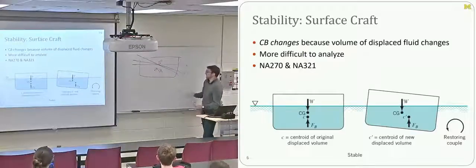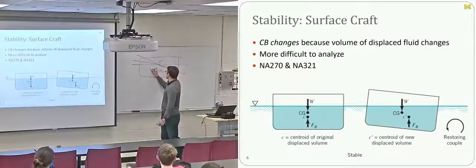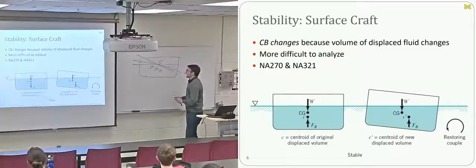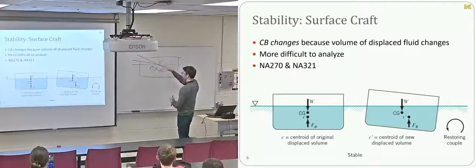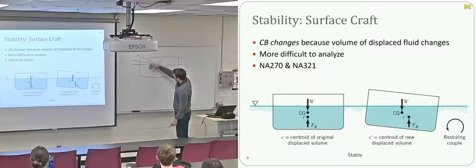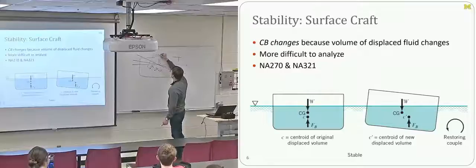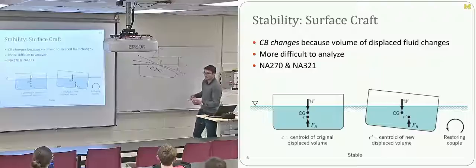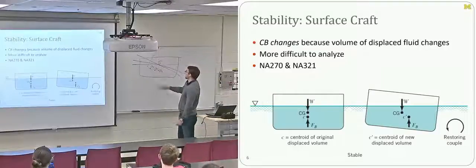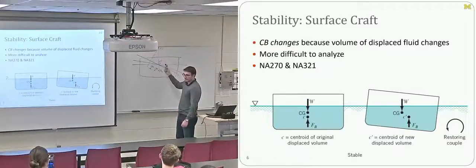And then again, as you roll to angle C, and you're removing more volume from here, adding more volume here, it's going to move a little bit more. So CB sub C. And the idea is that for relatively small roll angles, this doesn't hold as soon as you start actually rolling to angles this large, these are going to trace approximately a circular arc about the point that we call the metacenter, or the transverse metacenter. If you think about it, the metacenter is the point where the buoyancy will always act through for smaller roll angles.